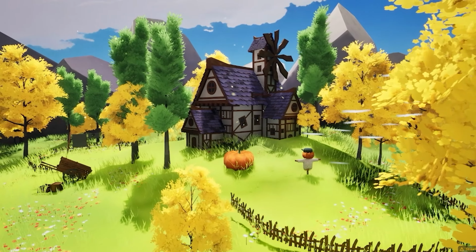Since our density filter is too similar to the grass, we add in an attribute noise node to efficiently re-randomize our points. From here, we can add another density filter node to reduce our points again to our liking. Once content, we can add in a transform points node as well as a mesh spawner again to implement our first set of trees. Trees spawned in on a slant, so to fix this I ticked the absolute rotation box on the transform node, which solved the issue.